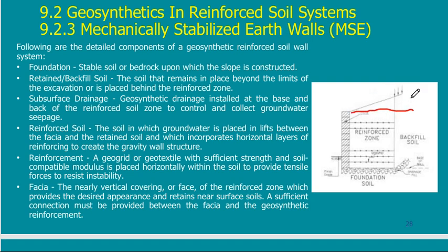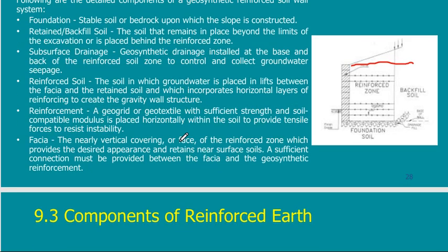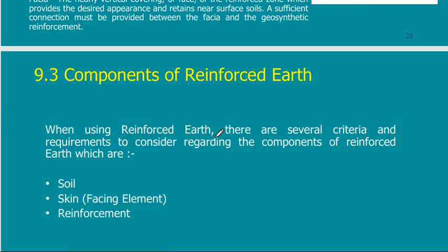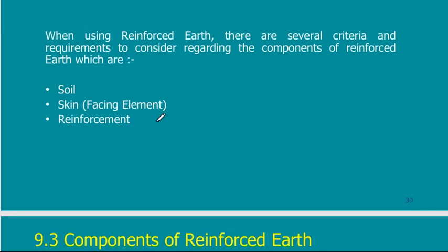The upper part will not have any reinforcement, but it will be considered as a load on top of my wall, and it will not have a big effect on my wall, not like a reinforced wall, because when I add load on top of my reinforced wall, I am increasing the stability of my wall. So in this case, having an inclined surface is not a very big problem to me, but maybe a benefit.